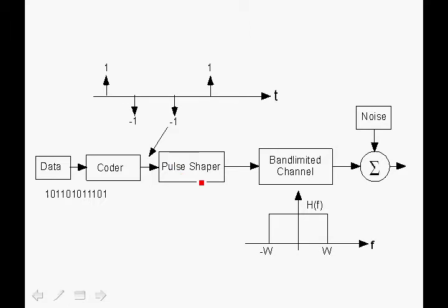So since the pulse shaper is a linear system and we have a chain of impulses, each representing a symbol, which have been mapped from the binary ones and zeros, the output of the pulse shaper is a superposition of the impulse responses of the incoming signal. And each impulse response, by the definition of the pulse shaper, will be band-limited to less than W hertz, and therefore we meet our requirements in terms of the baseband digital communication link.